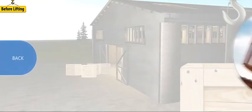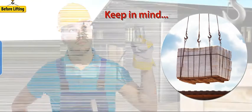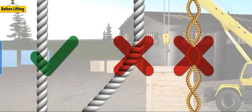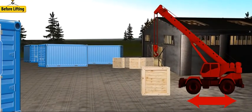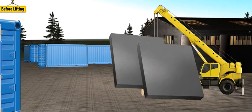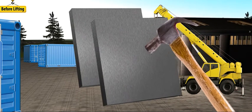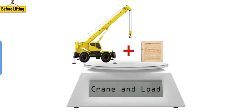Before you try to lift anything, there are a few things you need to keep in mind. First, make sure that the hoist rope is not kinked and that multiple part lines are not twisted around each other. The crane or hoist must also be kept in a level, stable position. In many instances, you will need to do this by using outriggers, sometimes with supporting blocks. Supporting blocks need to be strong enough and in good enough condition to withstand the weight of the crane or hoist and the load you will lift.